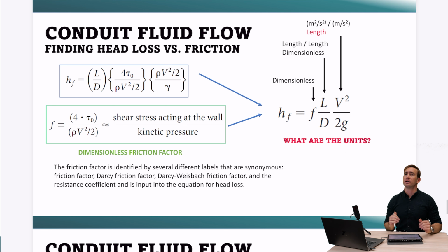So what do you do if the flow is not laminar? Now, to calculate the friction factor when flow is not laminar, you're actually going to need two pieces of information. Number one, you're going to need the Reynolds number, and number two, you're going to need what's called the roughness coefficient, or how rough the material of the pipe is. Essentially, the roughness coefficient is how many bumps, or how rough, the pipe actually is. So you can see that the higher the roughness coefficient, the more notches and more chances to develop turbulence and kind of lose energy there are.